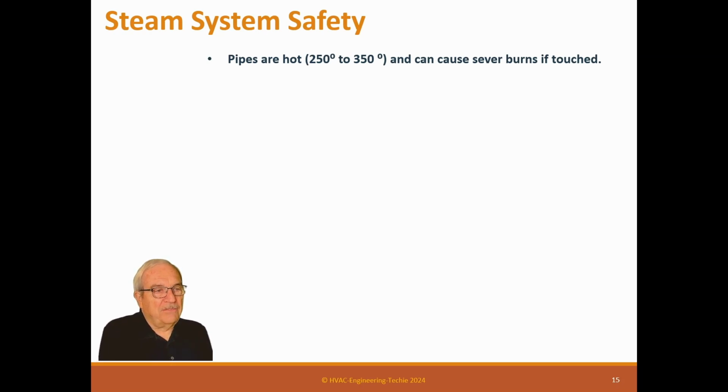So we couldn't insulate the valves. The valves had to be put sideways because the packing, when it was really hot, the packing would drip oil. So we had to put catch pads underneath them. And I had to hang signs on these things saying, hot, do not touch. And when I'd bring guests there to show them the system, because it's a pretty exotic system, solar-powered system, the first action, no matter who they are, a certified engineer, no matter what, they'd say, oh, really? And they'd put their finger and touch it. And that immediately burnt the end of the finger. I mean, it would just char the end of the finger. And I'd just say, no, don't do that. Trust me, it's hot. Because they just don't think about it.